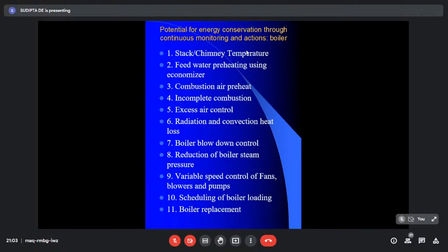But again, you have to find out the reason, because unnecessarily increasing excess air without any effect on the full combustion process will contribute to less efficiency, because the air is always added at a lower temperature than the boiler inside temperature. There are very interesting research publications on how excess air should be optimized in a boiler, but I'm rather helpless here not to explain those things, the basic physics. I'm just going to remind you that point 5 is the excess air control.